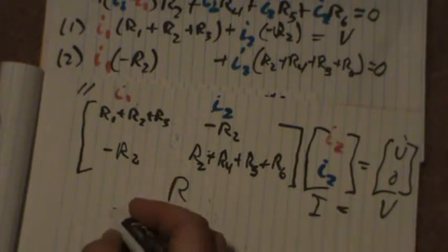And once I've generated them, I can solve for the I's by, if I call this AX equals B, so if I define this matrix in MATLAB notation and this vector, I can then just solve for it. And I'll just assume I've got the R and V here. And I can just say that I is equal to R backslash V. Or if you like calling this AX equals B, that's just X equals A backslash B. So there you go. That is how to do a simple mesh